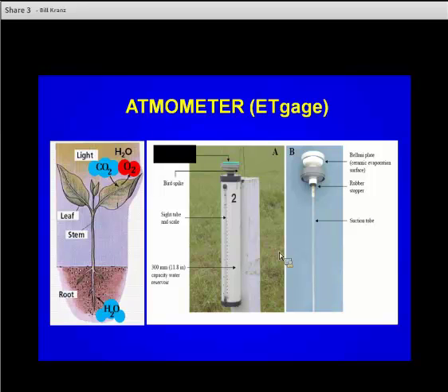type of cover. They have three different covers that you can purchase with these. In Nebraska, all of our weather data and estimated crop water use is based on our alfalfa reference crop. And so we utilize, I believe it's the number 54 or something like that, cover on this, because it was developed to mimic the water use for alfalfa. That's the cover on the very top of the Bellani plate in picture E. It's meant to mimic the transpiration of water through the plant leaves.